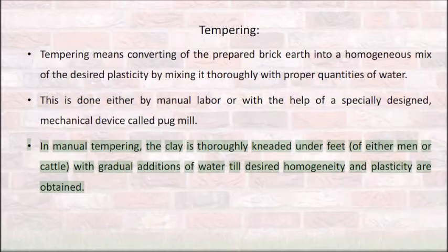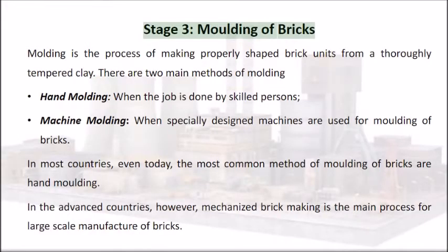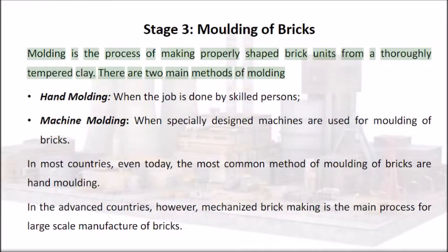In manual tempering, the clay is thoroughly kneaded under the feet of either men or cattle, with gradual additions of water, till the desired homogeneity and plasticity are obtained. Stage 3. Moulding of bricks. Moulding is the process of making properly shaped brick units from thoroughly tempered clay.